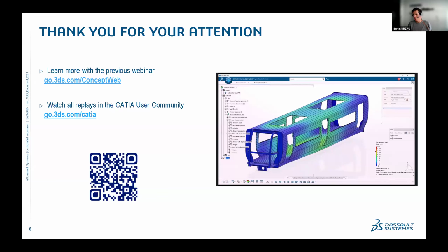And for the second question, the modules in visual scripting. As I said, the modules are watertight. When we used visual scripting to create the ribs pattern, we were in the wall center module. And as I said as well, visual scripting is not standalone, so it can communicate with conventional objects created in CATIA. That's what we did when we used the curve.